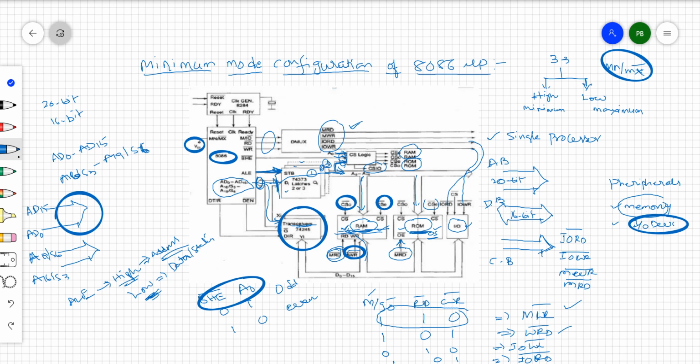So along with this data transfer, based on the control signal, these 2 control pins are there, which are output by the processor. One is whether data is transmitting or receiving. If the output is 1 from the processor, data is transmitting. That means the internal register data is transmitting to any RAM or IO, right? If this is 0, then it is going to be receiving data through the data bus from any peripheral, right?